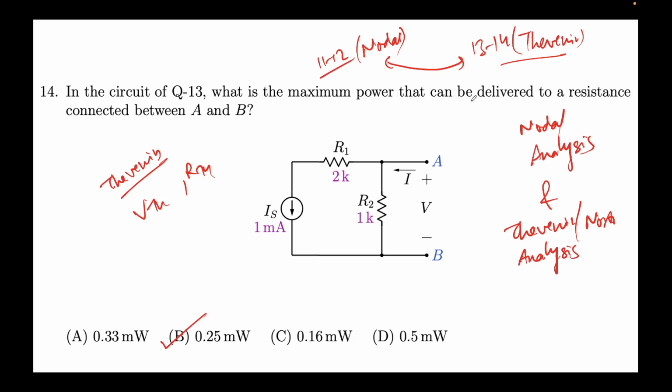We saw that problem where we had two independent voltage sources and one independent current source. What we did was deactivate two of the sources and solve for the first one. Then we activated the second one, deactivated the other two, and finally added up the voltage values to arrive at the final value.